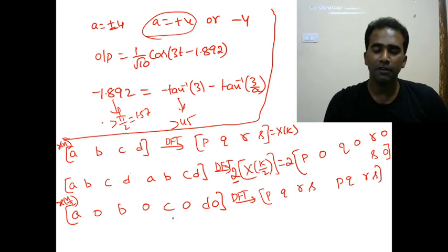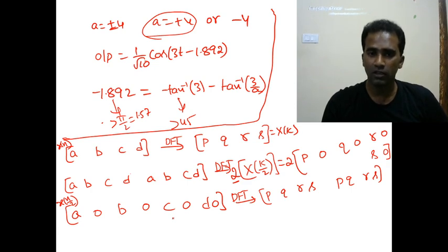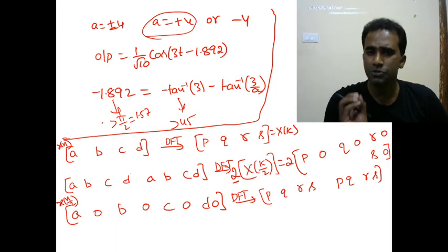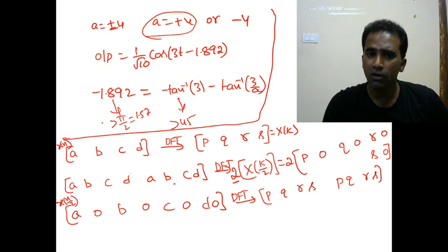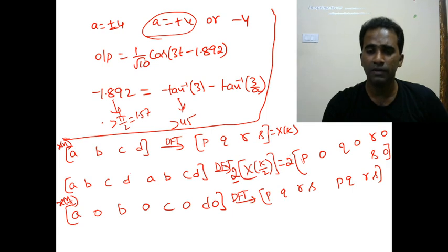So if you ever get confused whether there is a scaling factor or not, whether scaling in the time domain or in the frequency domain has a multiplication factor, just use a simple basic. The summation of all the samples will give you the first value of the DFT, right? So if the same samples are repeated twice, what happens? The summation will become twice, which means the first sample will be twice that of the previous case. So only when it is repeated in the time domain will there be a scale multiplication factor for amplitude in the frequency domain, only in the time domain repetition case.